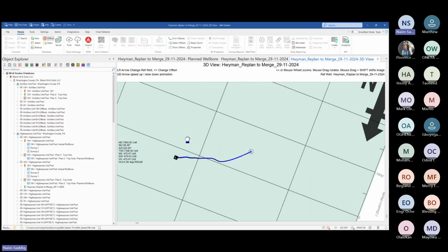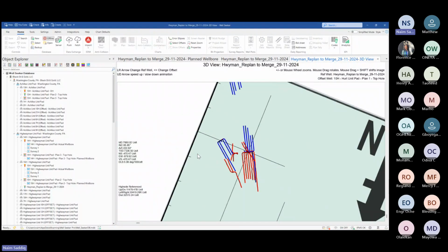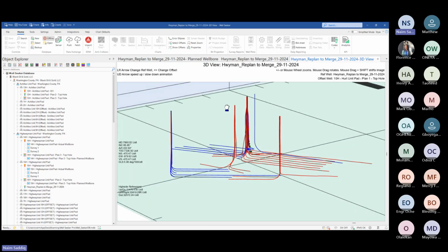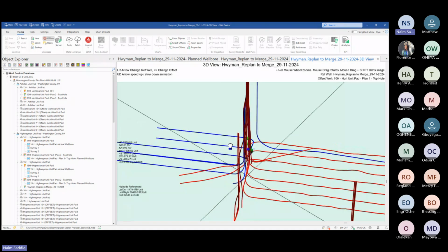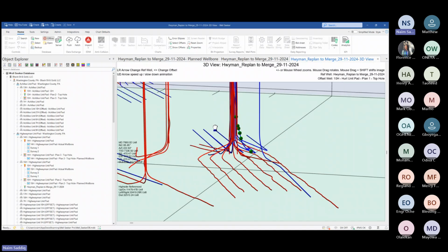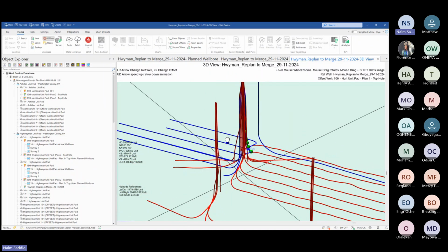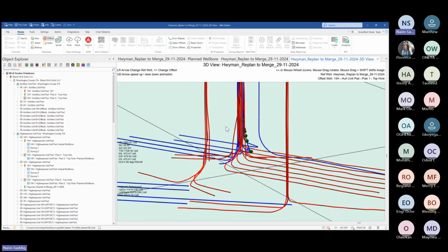This is showing a well that's being drilled. And if I want to show all the other wells in the vicinity, this is the US American fracking wells. You can recognize fracking wells because they are aligning in one direction. They are aligning just like a tooth comb, just like a comb. Why are they aligning in a certain azimuth? Because when they fracture it, the fracture should go up and down only, because they are aligned with the horizontal stresses.